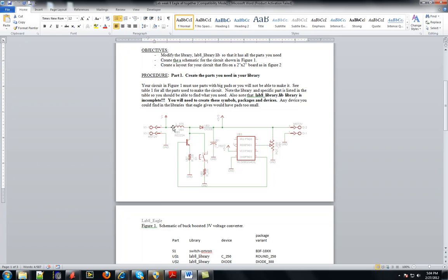So the way this works is this generates power. When this transistor is on, current can flow through this inductor, through the transistor into ground, and as it flows through the inductor it stores energy in the inductor. When the transistor is shut off, this becomes an open circuit, and now the only place for this current to go is into this capacitor. So what's happening here is that the voltage is monitored. This is my 3 volt stabilized side, monitored by the microcontroller. When the voltage drops below a certain value, it sends another pulse out here to the transistor, starting the process again, charging up the inductor, shutting it off, charging the capacitor, maintaining a constant voltage here.